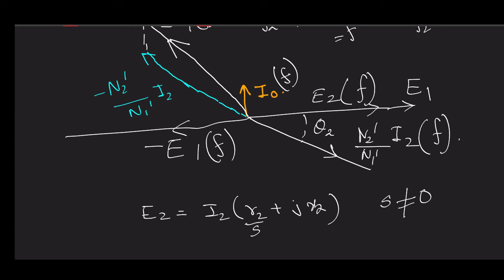That means an induction motor cannot reach synchronous speed, because once it reaches synchronous speed, the rotor current will become 0, and thereby the torque production will become non-existent, and due to that there will be no torque to overcome the mechanical retarding force continuously acting on your rotor mechanical part.